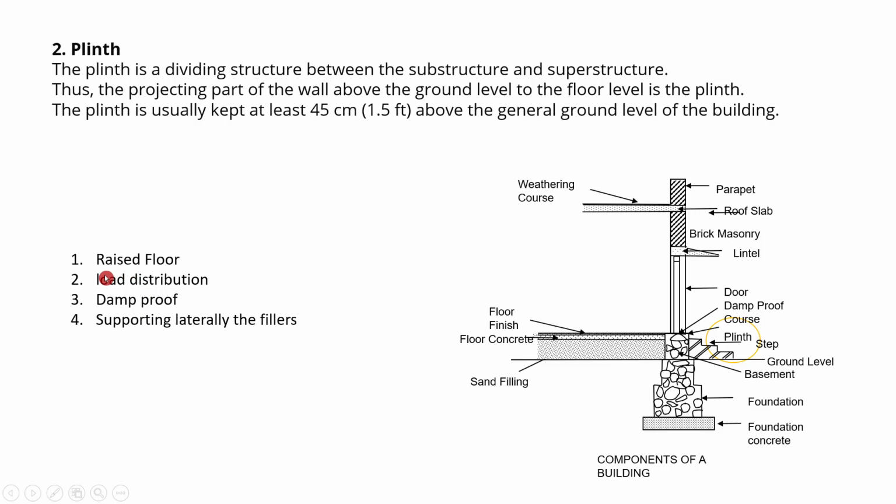We'll see the raised floor, load distribution, damp proof, and the supporting laterally the fillers. That means the plinth is meant for providing a raised floor to prevent the entry of water, to solve the issue of settlements, to properly distribute the load to the foundation, for providing the damp proof course for preventing dampness, and for supporting laterally the fillers.